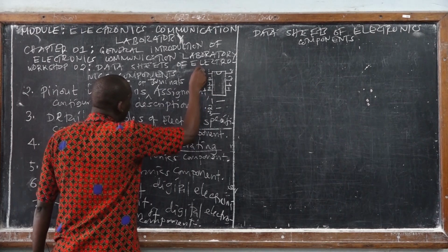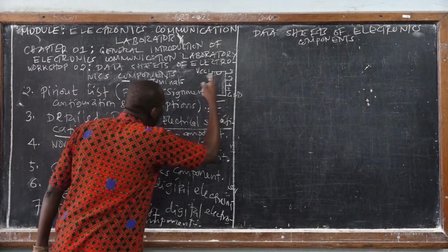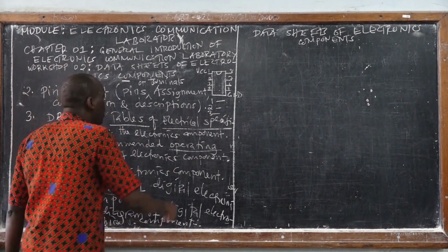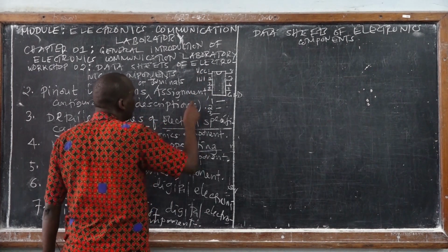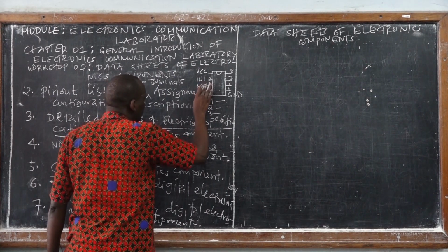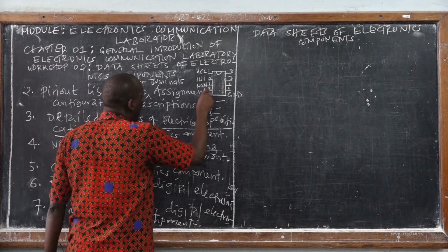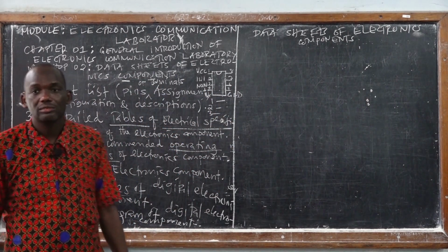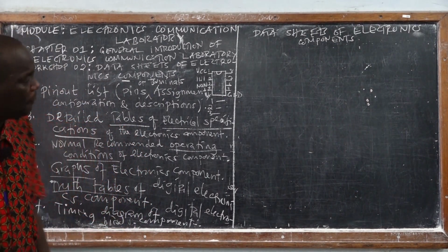In pin assignments or pin configuration, you can see, let's say, pin number 1 is VCC, pin number 5 is ground. So you'll see the labelings and the naming of the pins. Pin number 2, let's say it is the inverting terminal. Pin number 3 is the non-inverting terminal. Pin number 7, it's the positive power supply. That's what will be here in this part. Are we together?